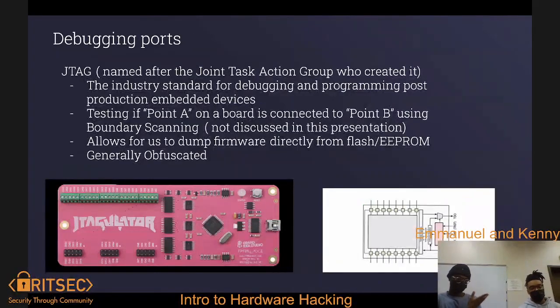Okay, this is me. So although we use UART in this test, I did want to mention JTAG, because in most applications that you'll find, you'll be dealing with JTAG, which is named after the Joint Test Action Group. Like I said before, this is an industry standard included on most embedded devices, for engineers that want to actually debug their stuff.